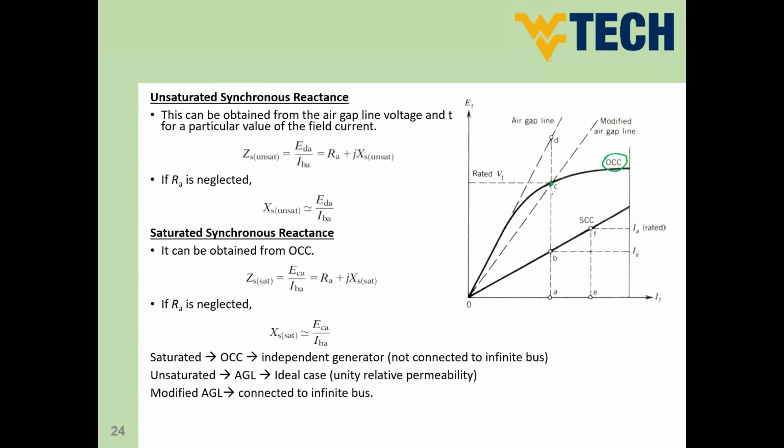So we are going to increase the volt not to the rated value, but higher than the rated value until having saturation. So how can you detect that? When you increase the current, you would find that the increase in the voltage is not that high. It's going to be like saturated. So the rate of voltage increase is going to be small. If the rate of voltage increase is small, you know that you are reaching the saturation, and for sure you passed already the rated value of the machine. So this is called the open circuit characteristic.